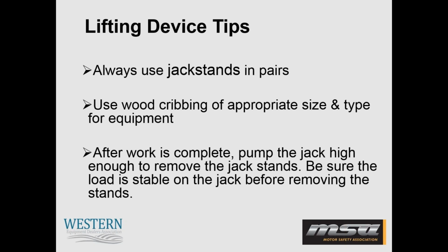And after the work is completed with the jacks, be sure to pump the jack just high enough to remove the jack stands. And then be sure that the load is stable before removing the jack completely. So hopefully those tips will give you some indications of safe lifting tips and being aware of blocking and jack stand usage.